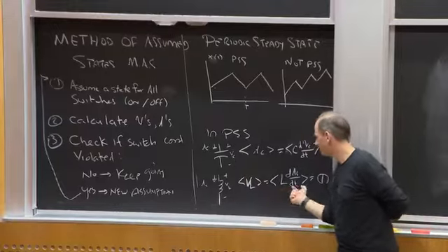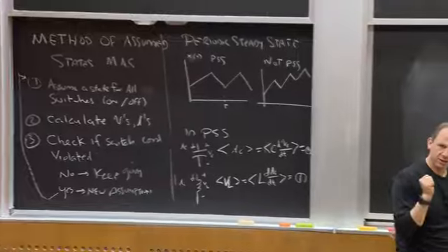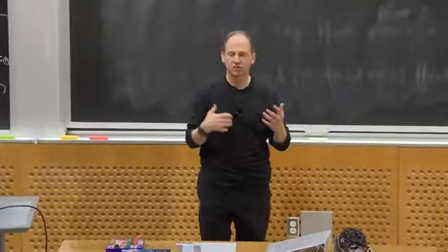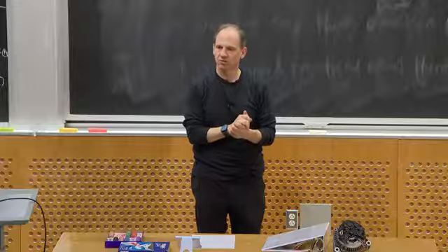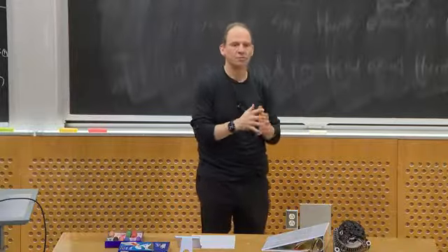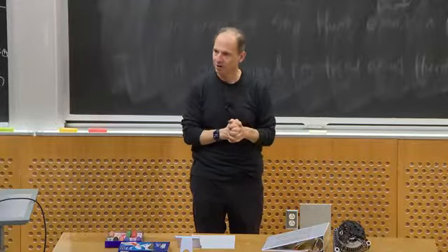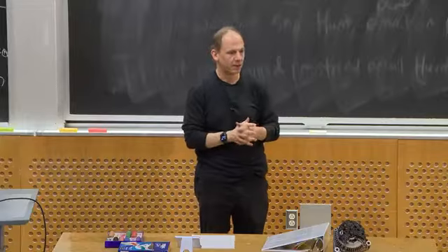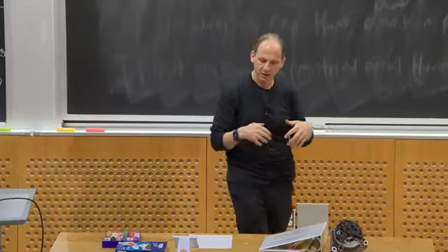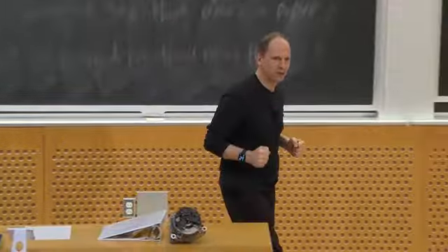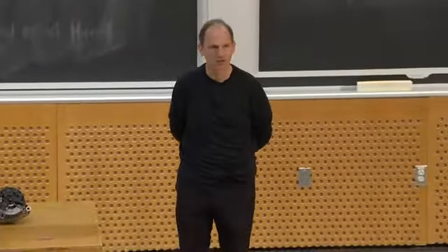Likewise, the average voltage across an inductor in periodic steady state is 0. So we can identify certain characteristics of circuit operation in periodic steady state, and we'll elaborate on this in upcoming lectures when we start talking about converter analysis. So that's a lightning review of what we talked about last class. Any questions before we move on?